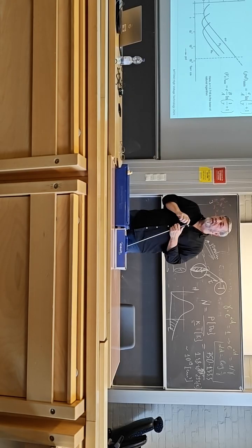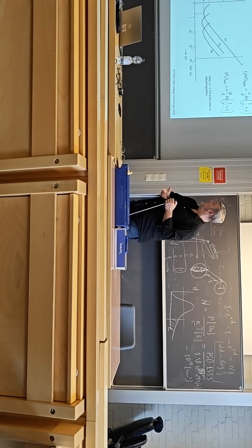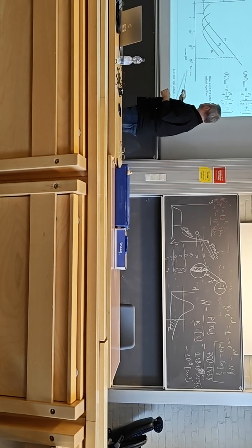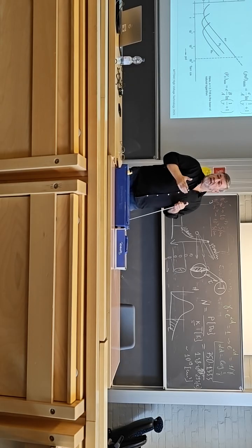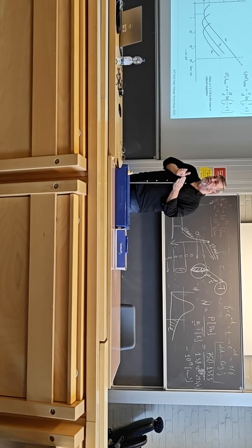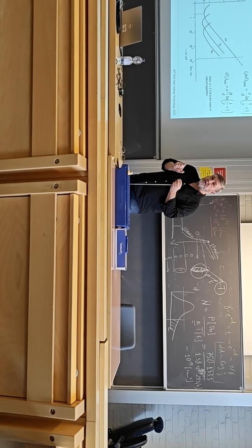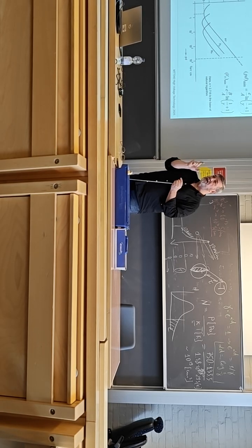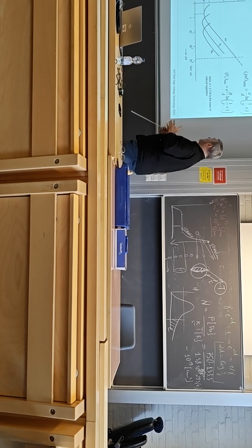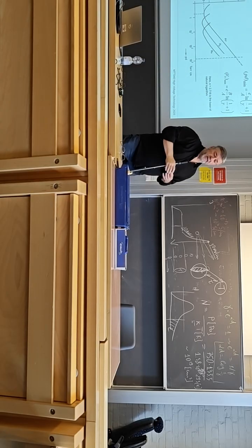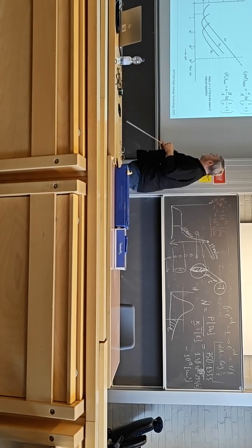So basically, this is all about conditions for ionization. At this pressure and distance, the free path is used kind of fully. You have an electron, which just over the corresponding free path gains energy exactly matching the energy needed for ionization. So the conditions are more or less ideal, and then you have the minimum breakdown voltage, minimum strength of the gas.